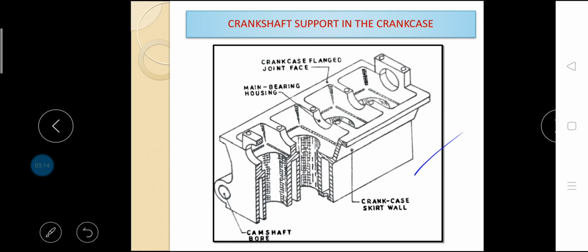What are those advantages? It is a good foundry material. It has high machinability. It does not warp under the high temperatures and pressures developed in the cylinders. Due to its slightly porous nature, it retains the lubricating oil film better. It does not wear too much. It has sound damping properties. It has a low coefficient of thermal expansion. It is relatively cheap.